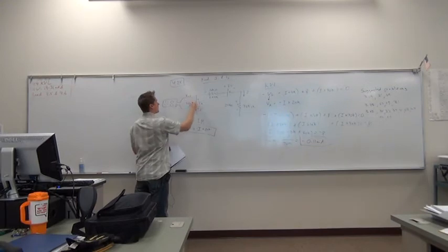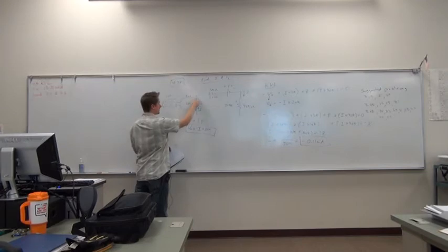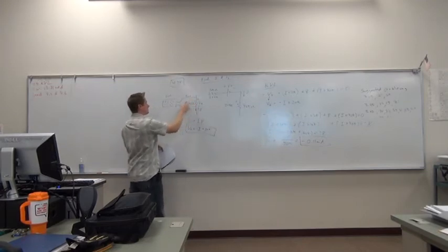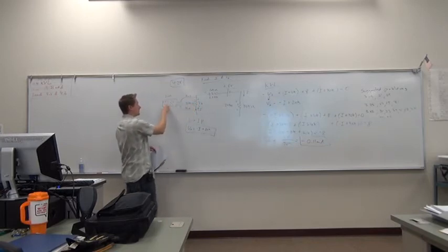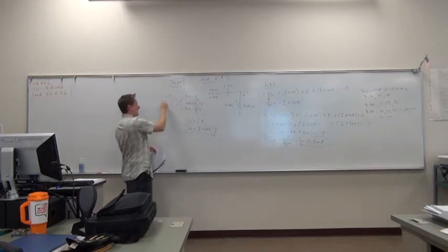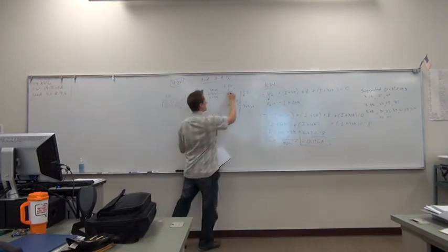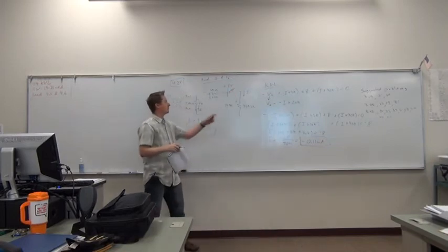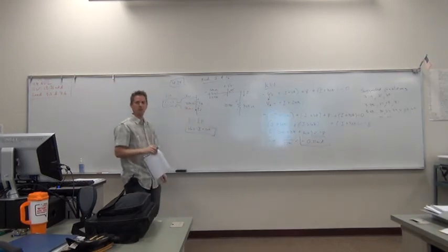For example, let's say that you have this voltmeter. You have the red lead connected here, and you have the black lead connected here. What that means is you've assigned a reference polarity of this being plus and minus, because if this value turns out to be plus, then you know what direction the voltage is. If it turns out to be minus, you also know that direction. So that assigns the reference for that. Another thing that's perfectly feasible is that this could be a variable voltage where the current could flip back and forth. In that case, the current could change back and forth.